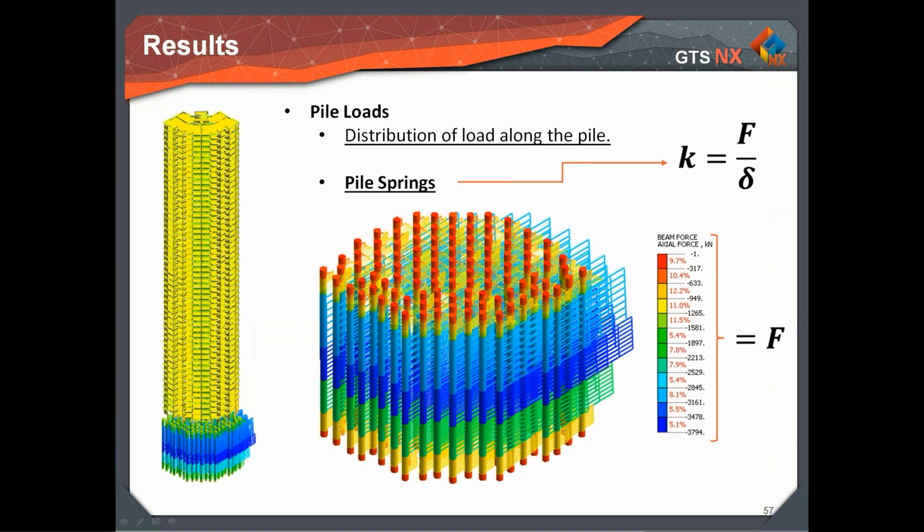And the very same thing can be done for area springs. This is a Piled-Raft hypothesis. Values of pressure above the raft might be divided by the settlement obtained at the same point. So this also might be sent to the structure team or exported to MIDAS Gen.